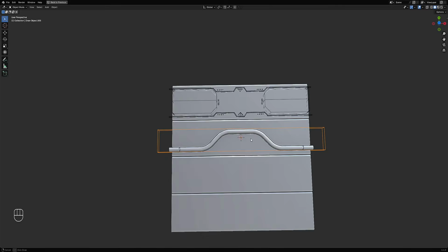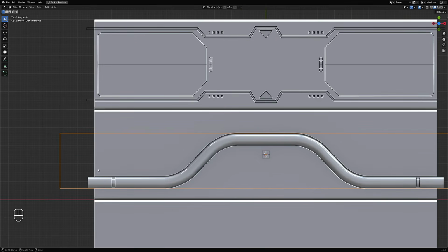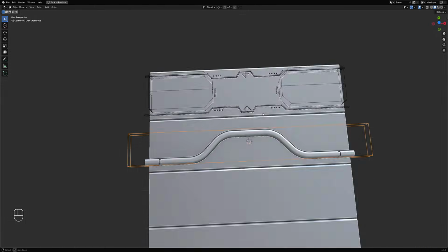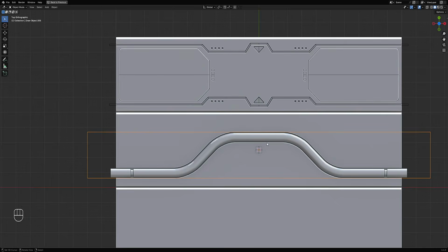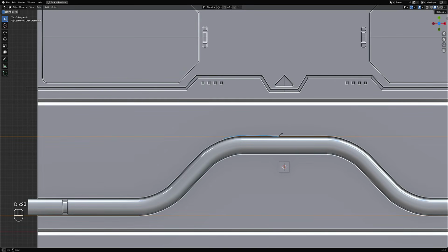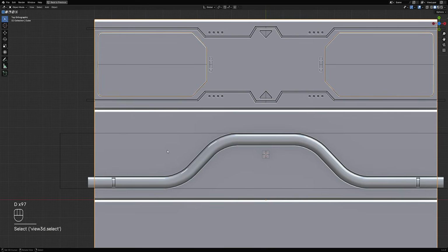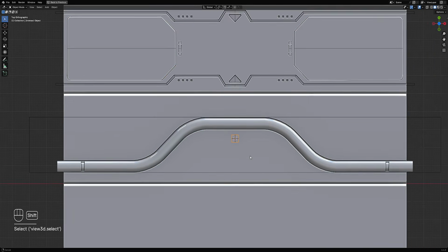Using visibility, so we're going to withhold on that. I am going to apply this. They're not going to stay modular, but seeing that I'm not really sure on applying this Boolean objects up here, I'm just going to delay on creating those bevel details on this part here till late in the game, where I am sure that I'm going to actually apply the Boolean modifier on this part.